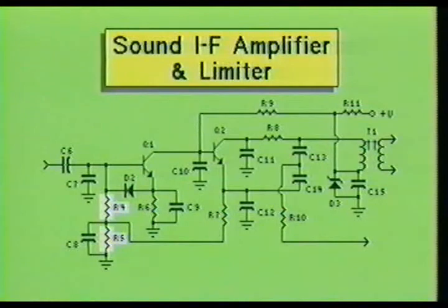Resistors R4 and R5 form a voltage divider to supply transistor Q2's emitter with the correct DC voltage level. This voltage level biases transistor Q1's input to limit the positive half of the incoming waveform. Resistors R4 and R5, in conjunction with resistor R7, also provide negative feedback to transistor Q1. Capacitor C12 acts to regulate the negative feedback voltage.